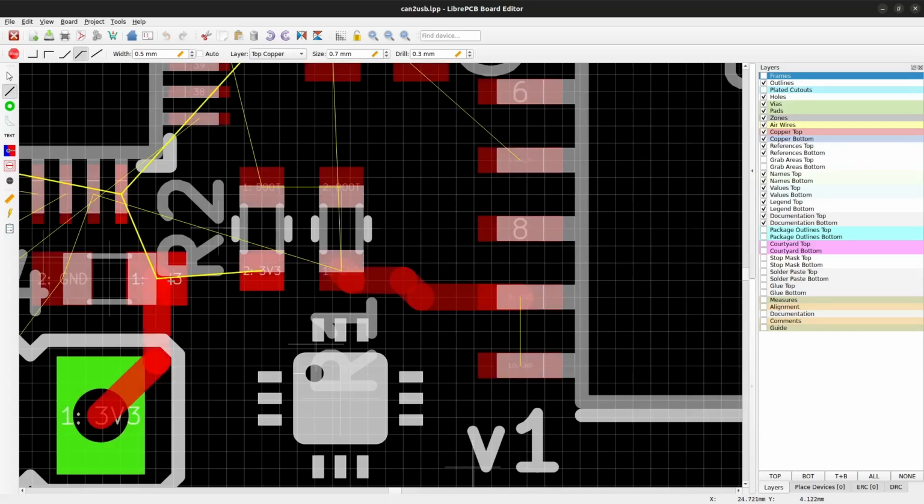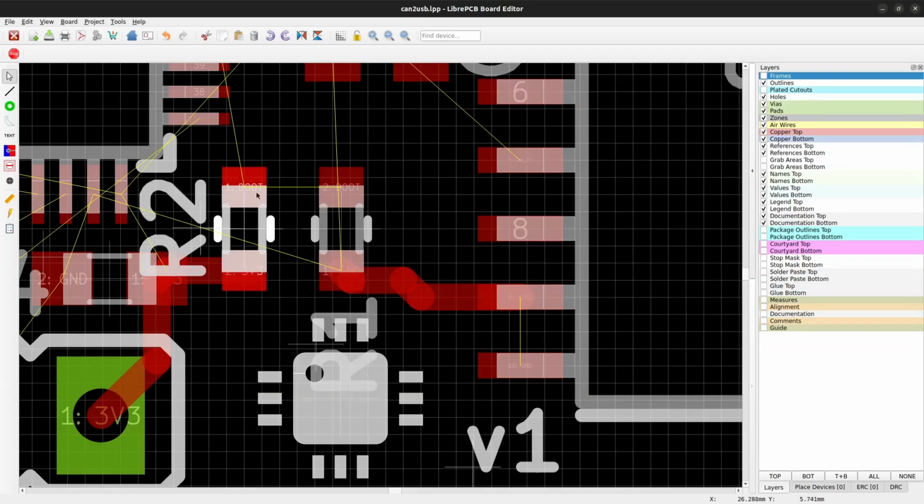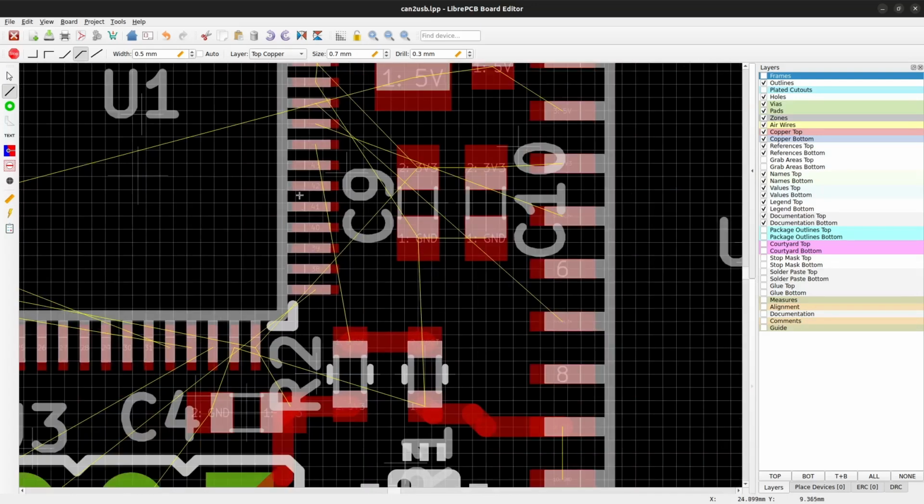To quickly move a device, the tool can be exited with a right-click on the background. Afterwards, press the right mouse button again to switch back to the Draw Wire tool. Just make sure there's no object below the cursor, as this would open the context menu.